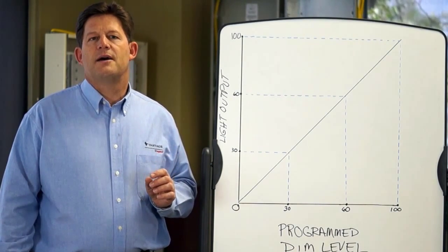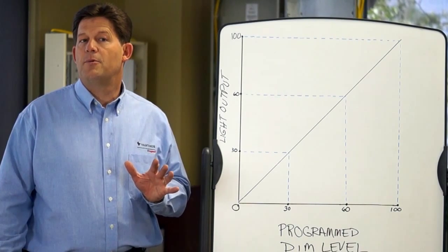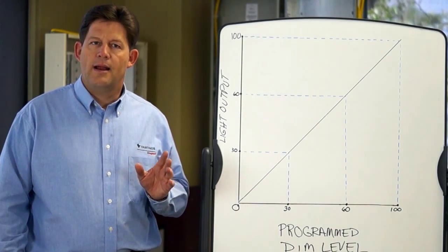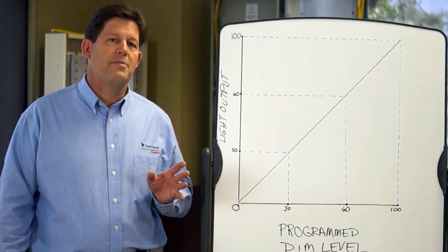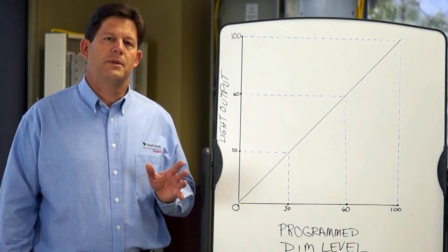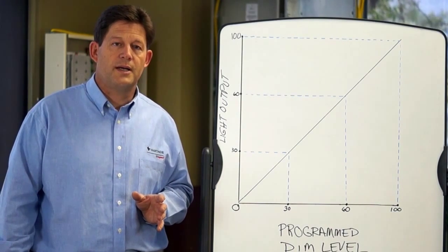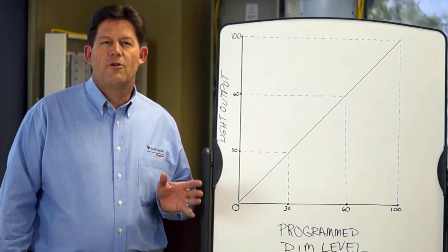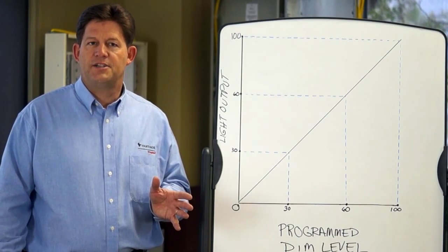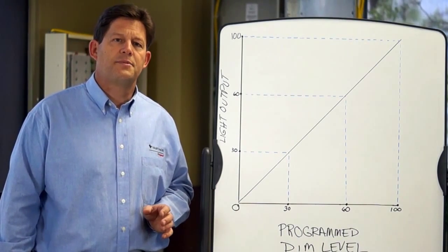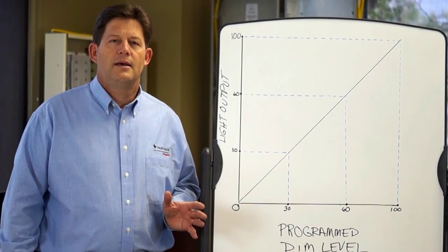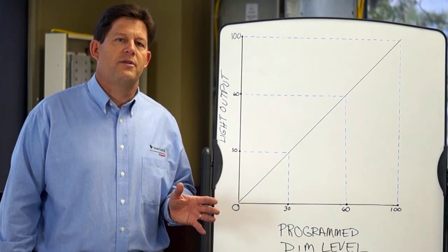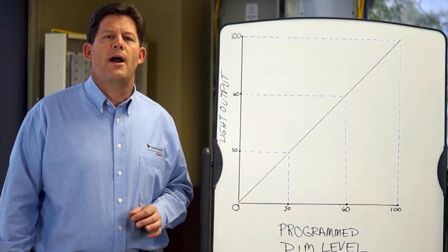A skilled lighting designer distinctively knows what levels he or she wants to achieve, and unless the linearity is good, valuable time may be wasted in adjusting the programmed dim levels to compensate for deviations from ideal linearity. Furthermore, once scenes have been set in a Vantage house, and then later incandescent lamps are replaced by LED lamps, unless linearity compensation is made for the new lights, all scenes would require recalibration.